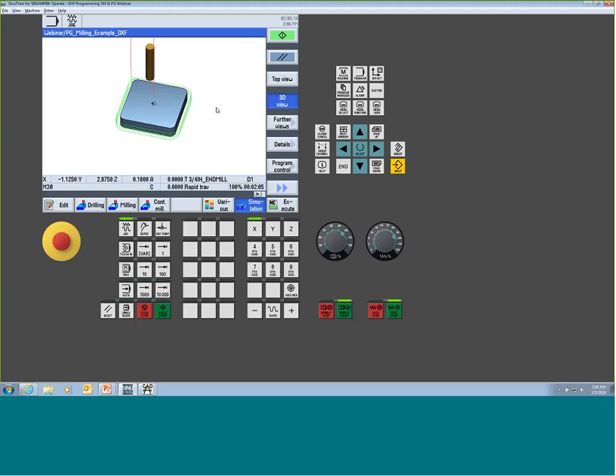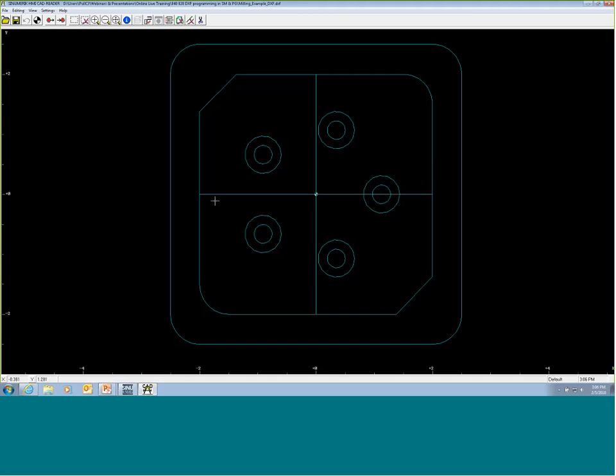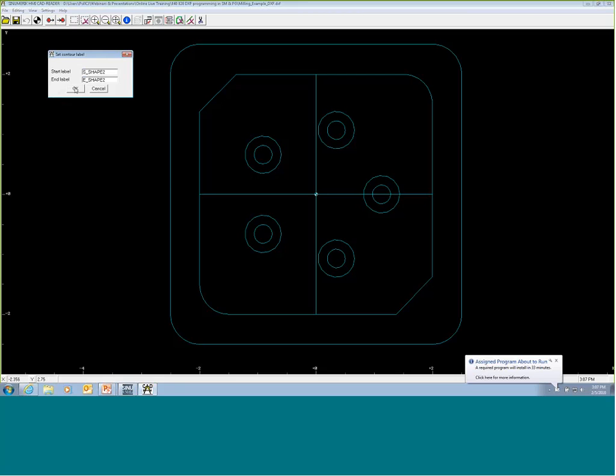So the labels are really the trick. You want to start to use those label features. When you go to do more than one, like we have a whole separate feature right here, when I go to do the next one, I want to make sure I come in and recreate my labels. You pick the label first before you go to grab anything, because you don't get the option to select the label afterward. So I'm going to call this start underscore shape 2 and end underscore shape 2. All right, we're going to say OK.